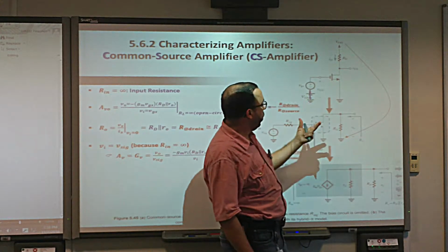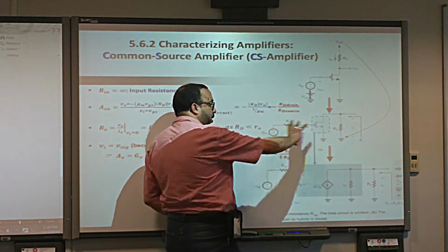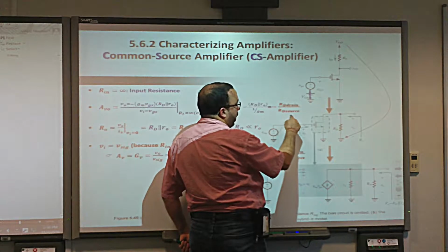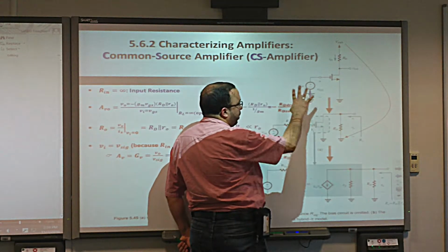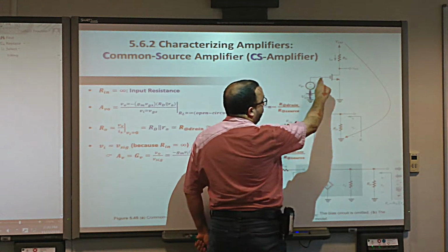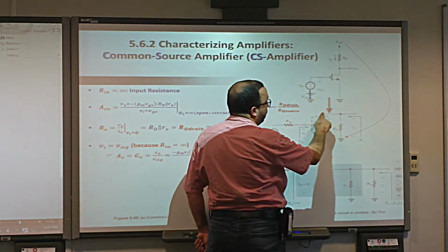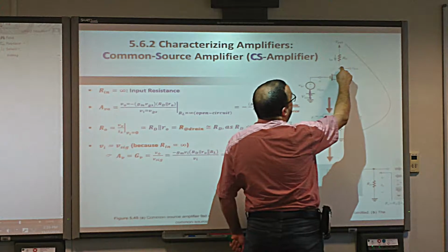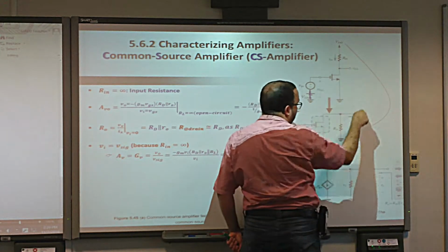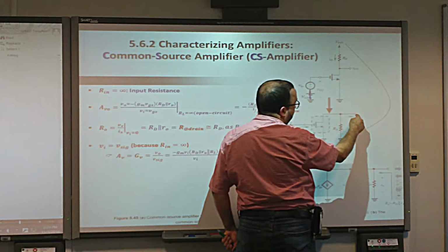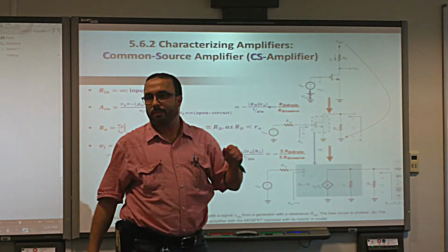Okay? So what we will have is this circuit. We'll have an AC voltage there. It has, of course, its internal resistance. And then it goes to the gate of the MOSFET. The source is to the ground. The drain comes here. From the drain, from this point to the ground, I have RD. And the output is taken at the drain. Okay, got it?